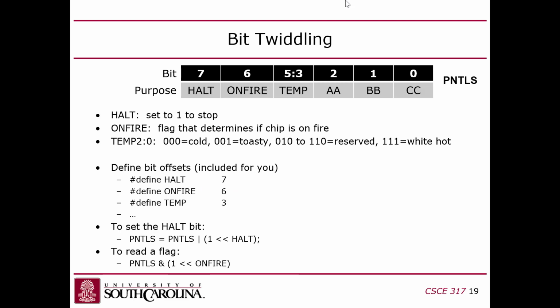So these registers are mostly comprised of individual bits that have a specific purpose, or ranges of bits like fields that have a purpose. Whenever you access one of these control registers or status registers, you have to do something called bit twiddling, which means that you have to access, read and write specific bits, as compared to what you're used to doing, which is treating a word or a variable value as just one monolithic value, right? Like in Java, you declare something as an integer.